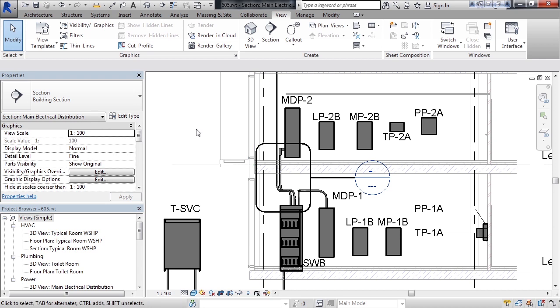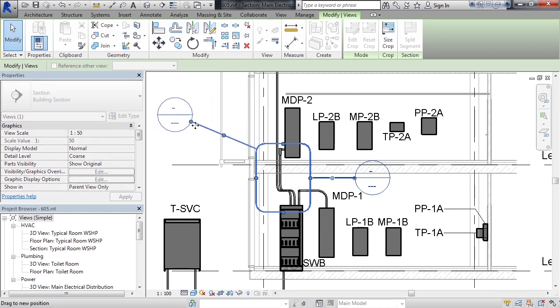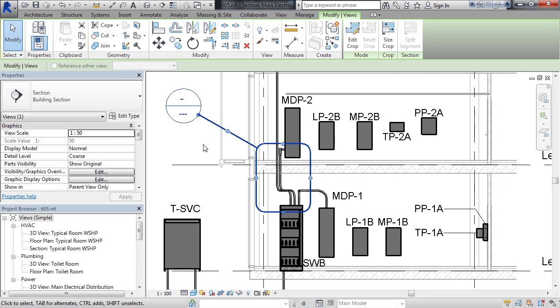Now to move the actual callout symbol, simply click on the actual callout frame or line connecting the symbol to the actual callout rectangle, and then you'll see a little circle appear next to the callout. That callout circle can be moved now by using the drag handle that's attached to the circle. Just hold your left mouse button down over it and move, and you can drag this callout symbol along with its extension line to a new position and then release it.